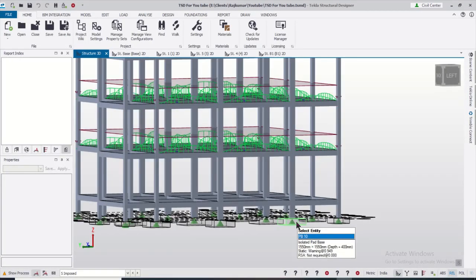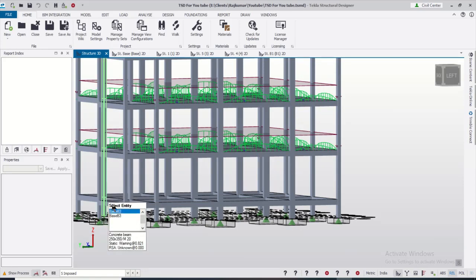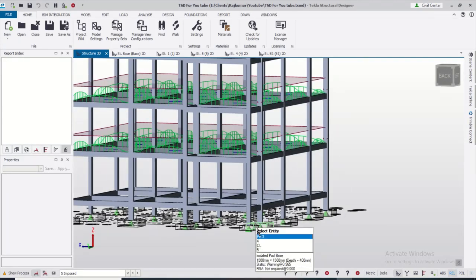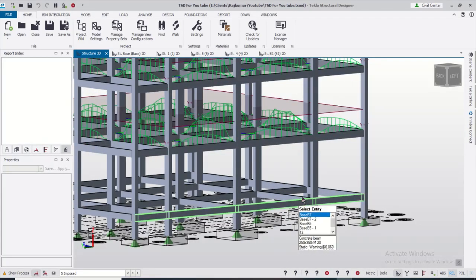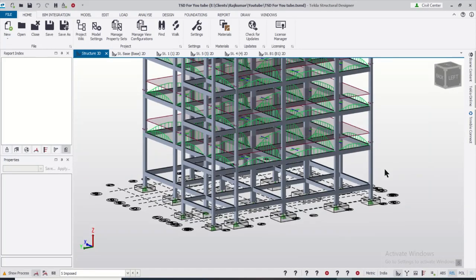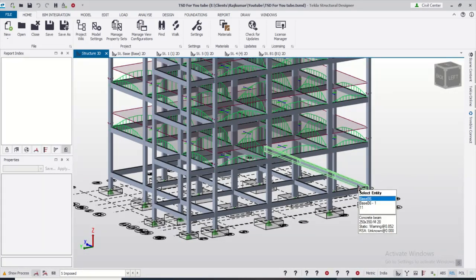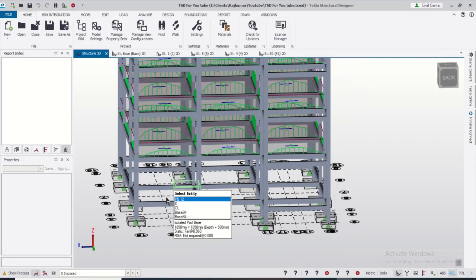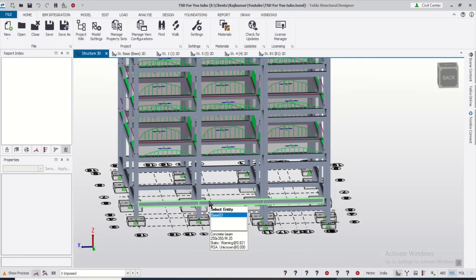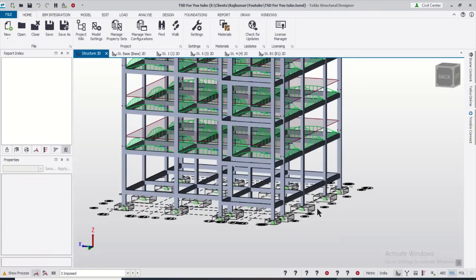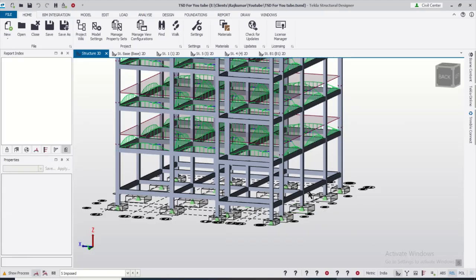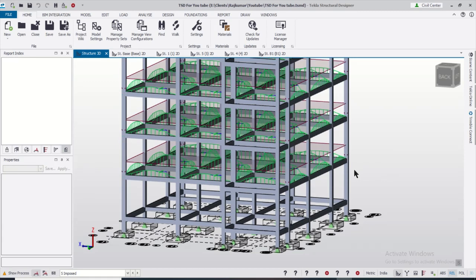The plinth level is basically the level at which the floor of the building starts. Usually buildings are made at a particular height above the ground level, that is called the plinth level. The plinth beams bear the load of the walls above them and their self weight, but they don't have any load of slab, because at plinth level sand filling is done inside and PCC is given above it. So the load of slab is not there, and that's why live load is also not present in the plinth beams. So the sizes of the plinth beams will normally be less in comparison with the roof beams.